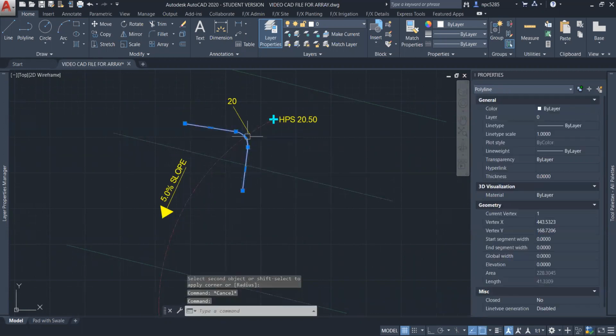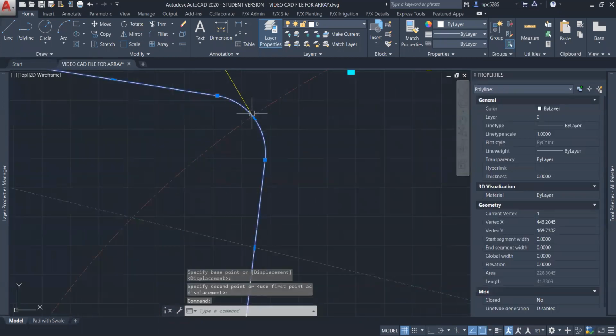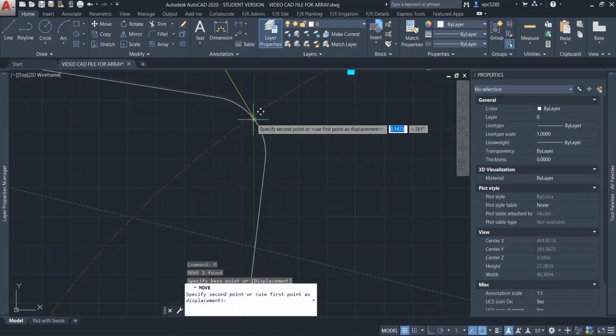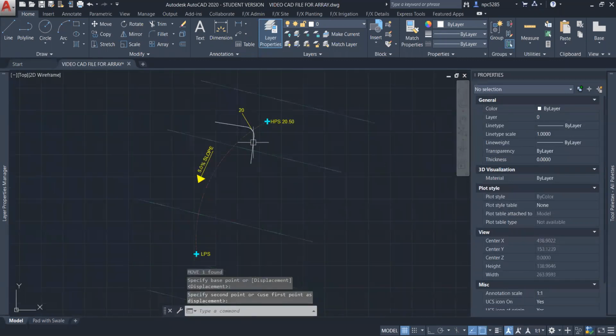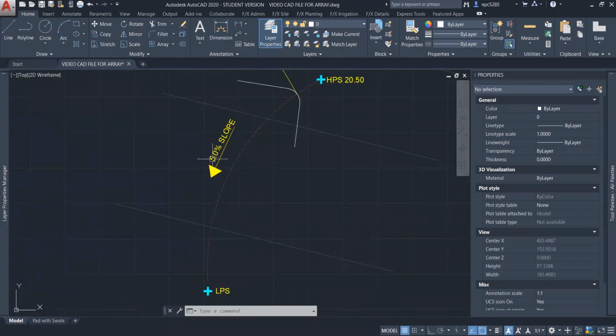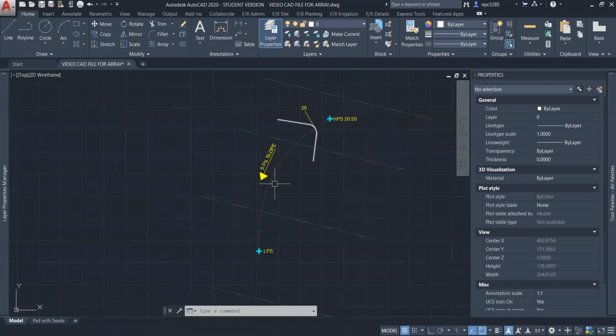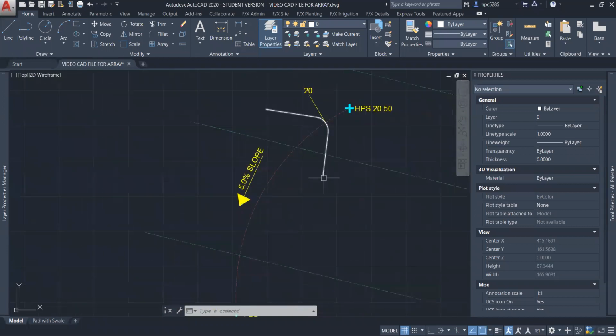And then I'll take this object and make sure that the tippy top of it and the dead center of the swale formation is exactly where that line hits. So from this point on, it needs to be at a 5% slope. From here to here, if it's 10 feet, it's 20 feet between whole contours, and that's a 5%. Then the rest of this, we're looking for the whole contours.